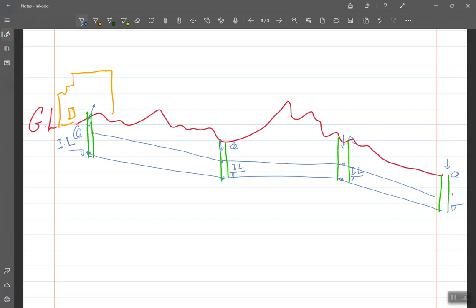So to define the manhole, or the junction, you should define the invert level, because the orientation or the slope of the pipes connecting each two junctions will be determined based on this invert level. And of course, because we are dealing with open channel flow, we can only use pipes that are sloped to a certain point. You can't have pipes that look like that, because we depend on gravity flow.